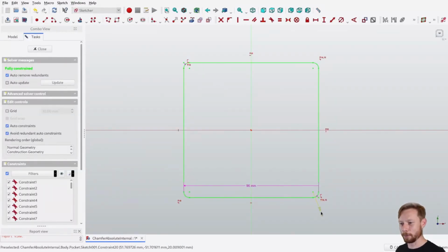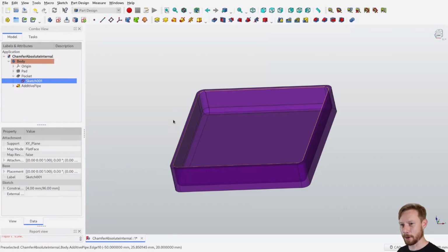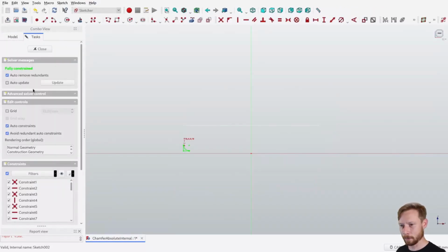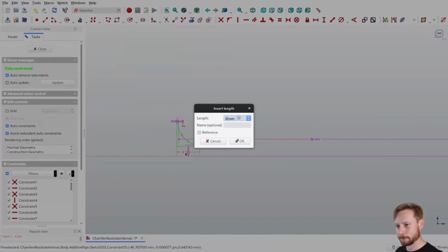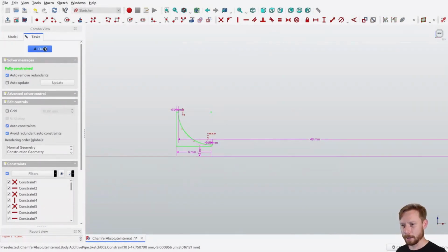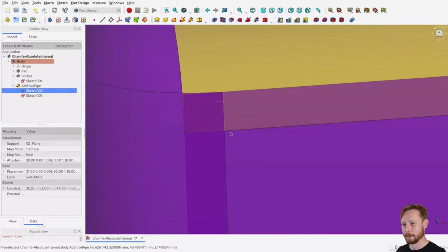So I've got a little 4mm radius in this corner of our sketch. And if I go and change my fillet profile to something that is larger than that value, so 4mm corner, so we'll make this 6mm. And yeah, now we have broken geometry, so we can't move forward with this model in this state.